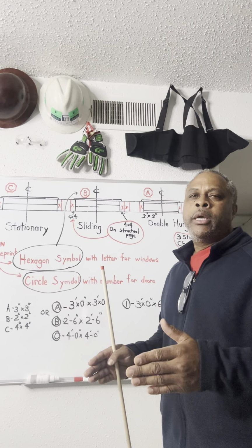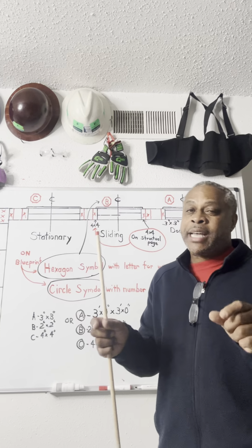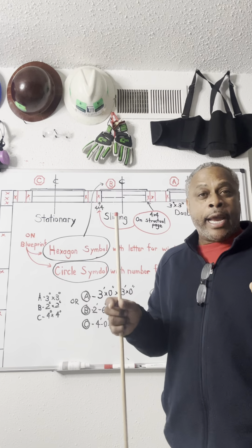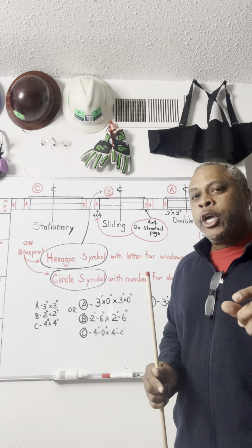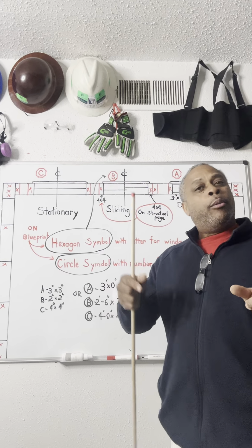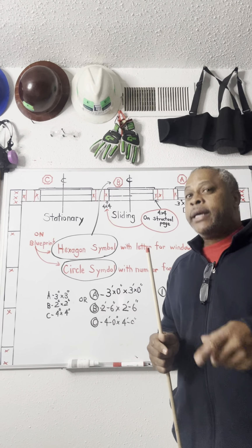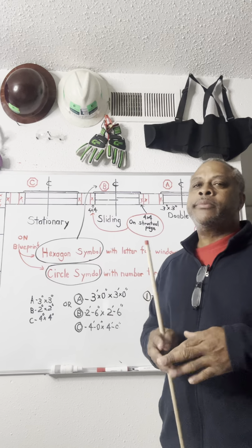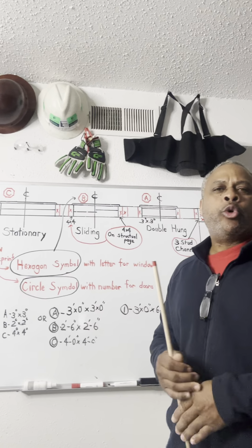It gives you plenty of room, because you have to allow for the 3/4 of an inch for both sides of your jamb. 3/4 plus 3/4 is 1.5 inches. You've got a trimmer or jack, 1.5 inches, and 1.5 inches on the other side. That's 3 inches, plus another 1.5 inches. That's 4.5 inches, so 5 inches. That gives you plenty of room for the door hanger.